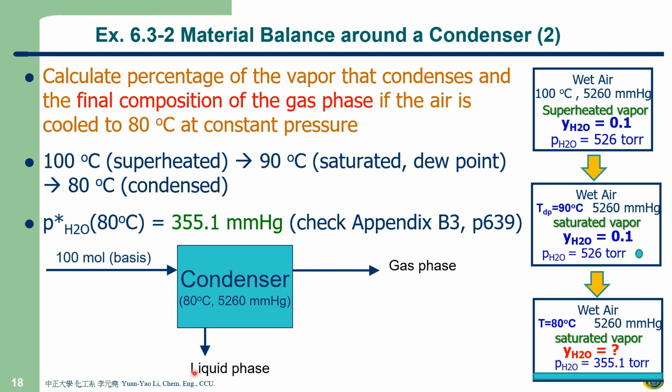Okay? So the input will be, for example, 100 mole basis, right? And then you have 10% water vapor. And what's DBA? Bone dry air, B-O-N-E, bone dry air. That means no water anyway. So 90%. And temperature 1,100, and then total pressure.